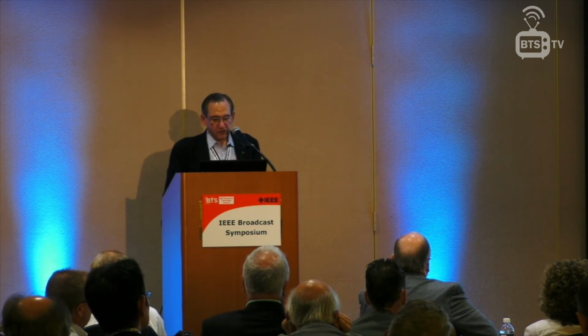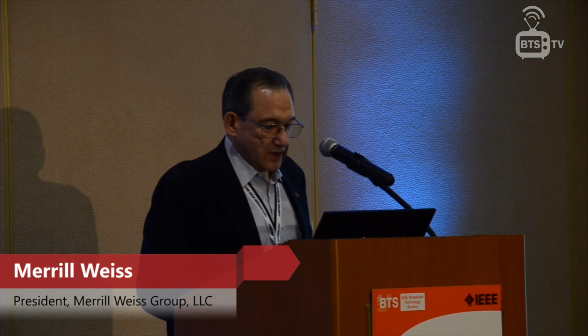For channel 14, the issue is to protect land mobile. There are three sources of the interference: the transmitters, PIM in the environment, and receivers. Transmitters and receivers can be treated with filters, but PIM means cleaning up the environment. And interactions with the land mobile operators will be part of the process.